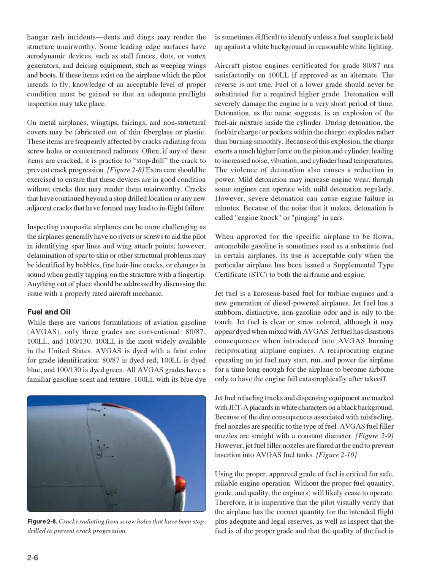Because of this explosion, the charge exerts a much higher force on the piston and cylinder, leading to increased noise, vibration, and cylinder head temperatures. The violence of detonation also causes a reduction in power. Mild detonation may increase engine wear, though some engines can operate with mild detonation regularly. However, severe detonation can cause engine failure in minutes. Because of the noise that it makes, detonation is called engine knock or pinging in cars.